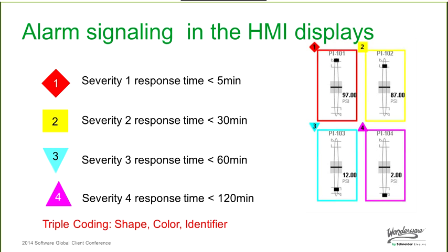And when looking at alarms, you should also keep in mind the response time for the alarms. So you're not flooding your operators with critical alarms when they could be high. You have to look at what is the response time for them.